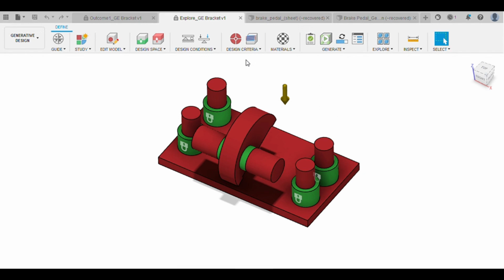And finally, load conditions. So load conditions we could input here. So structural constraints, fixed geometry, all of that we can input. And the structural load conditions, what load conditions are being placed in this design, we can input. And with respect to the design criteria, the objectives. So objectives, there are generally in Fusion 360 two objectives, that is minimizing the mass and maximizing stiffness. So we can select one of these. And with the limits, safety factor limits, the strength considerations, whatever safety factor we need, we can input.